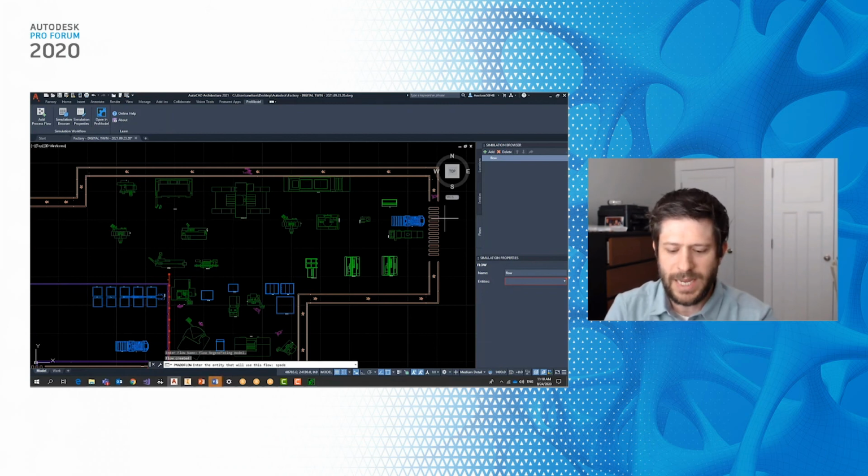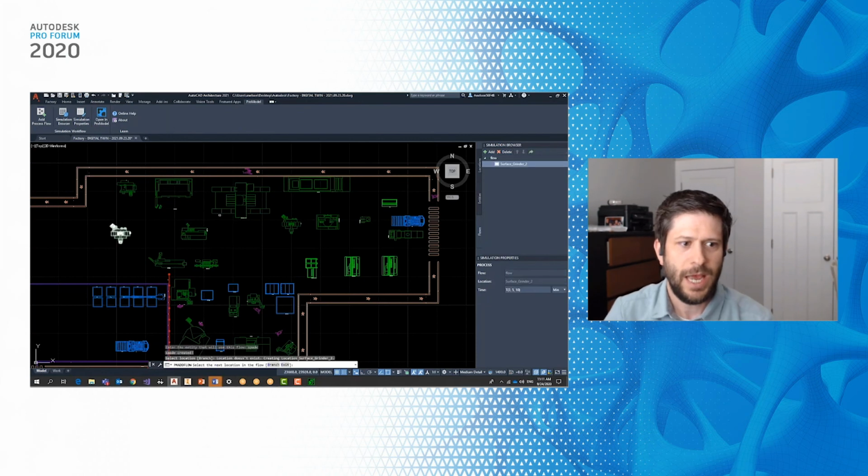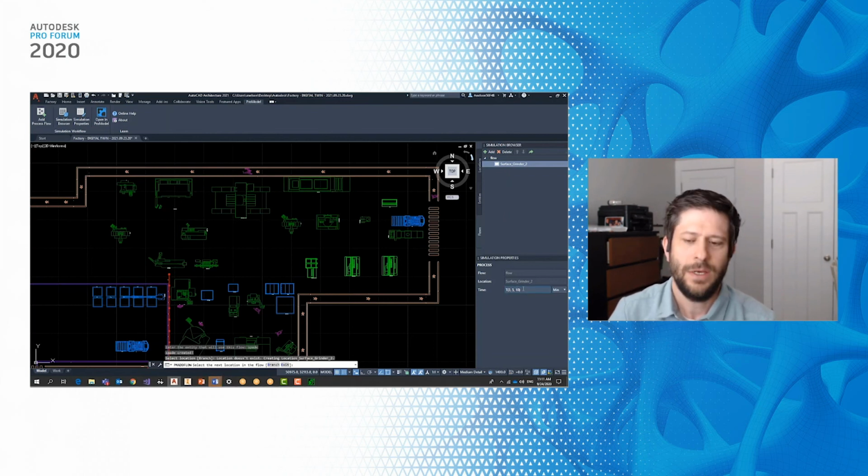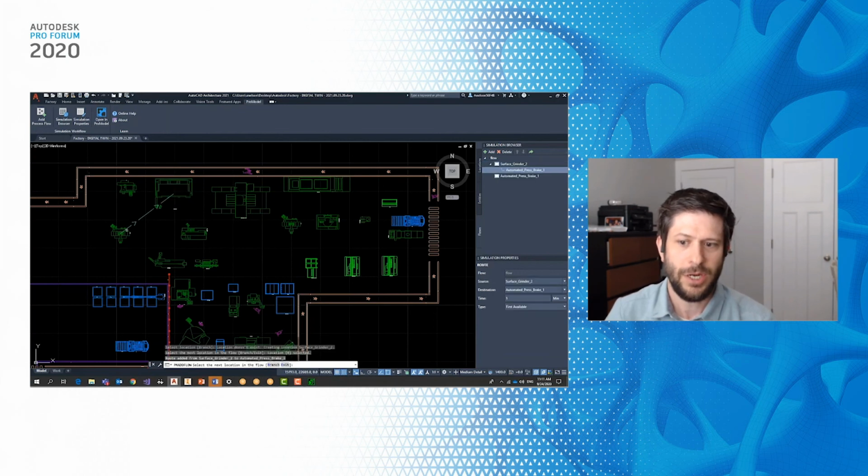And then I'm going to pick an entity. And I want this to be the spade, like in the model that Andy was showing you. So I'm going to hit spade, hit enter, and then I will start selecting assets that I want to be in my simulation and be part of this flow. When I select it, it will automatically start to add the location. If it didn't exist, it will add it. It's a really cool feature, along with properties that belong to this location, how long our entities will process at that location.